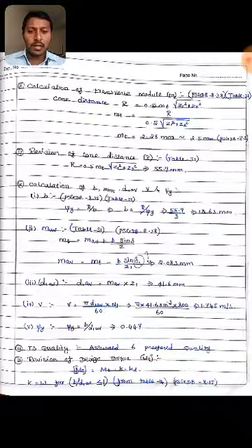Step 10. Calculation of b, MAV, D1AV, V and psi y. First, to find out b. From PSG data book page number 8.15, table 13, psi y formula is R by b. To rearrange the formula, b is equal to R by psi y. Substitute the R and psi y value. Finally, we get b value 18.63 mm.